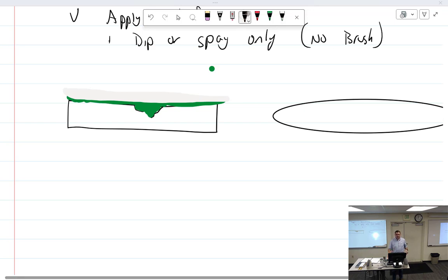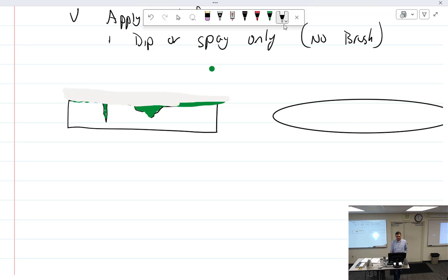Just talking amongst yourselves. Okay, so then what happens is, if we had maybe a deep crack like that, fill that in, maybe like that. Okay, and so we add the emulsifier, and now the emulsifier, based on time, should do something like this. But think about the method A that we did. Would you have both of those indications, or would method A have cleaned out this one? They probably would have cleaned that one out. Yeah, see, now you're going to get this indication here.